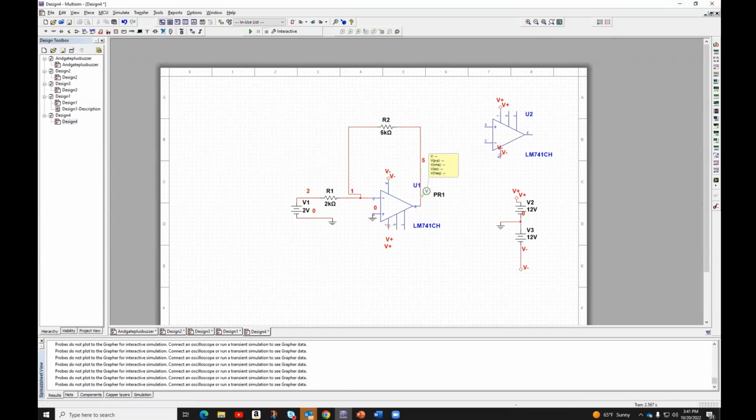So let me go back for a minute here. All right, so you see the use of it. Everything's cleaner. And again, you can reuse this later for other circuits. So let me get rid of this other op-amp because I'm not using it. As you can see now, I get the same result, because if everything is okay, then it means that I actually am connected to the negative here and to the positive here. And if you want to double check, you can bring probes and check it.